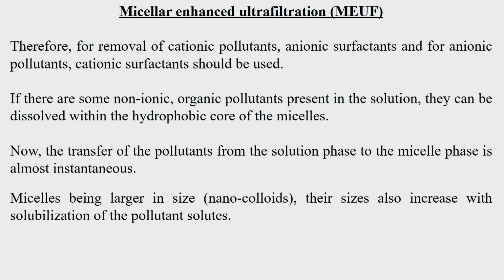Now, the transfer of the pollutants from the solution phase to the micelle is almost instantaneous, because the concentration of the solute inside the micelle is 0, whereas the solute concentration in the bulk is Cb. So, due to this Cb minus C micelle, the driving force is entirely the concentration gradient, that is, whatever the solute concentration is present in the bulk.